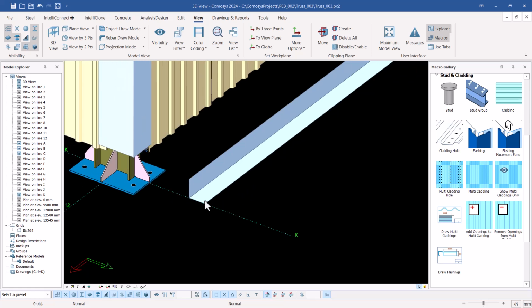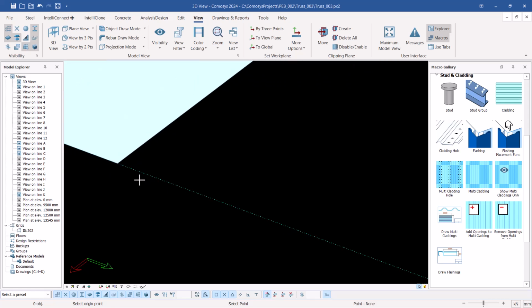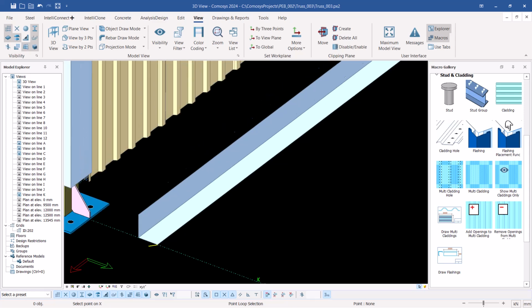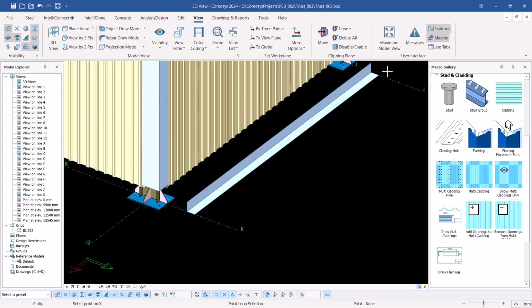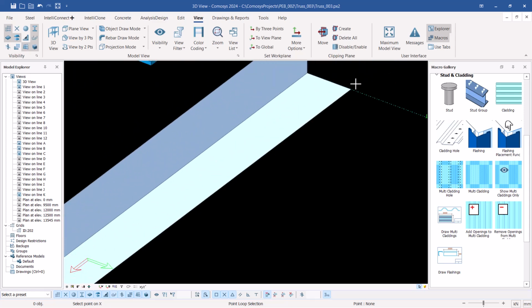So I'm going to have the second one and put them together and weld or join them together. I'm going to come back here and just mouse over on the same spot. Just place your cursor on top there, then move your cursor out and target the far end of the same member. We want to put them together.